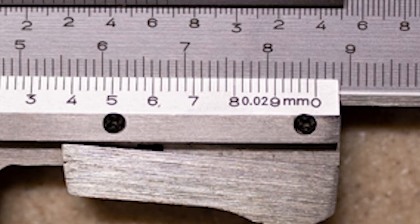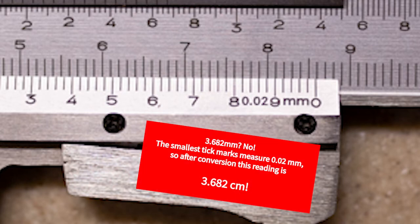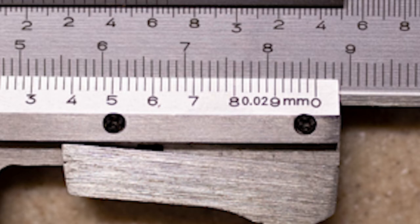And it seems to me that the first mark past 8 is the mark that lines up best with the mark above it. So that would be 3.682. Each one of those little marks on the scale is actually 0.02 millimeters, and that's how accurate it is, or potentially accurate it is. So 3.682 is the reading. And I read that with it under tension. And you can read anything up to 6 centimeters in any dimension to the nearest 0.02 millimeters.